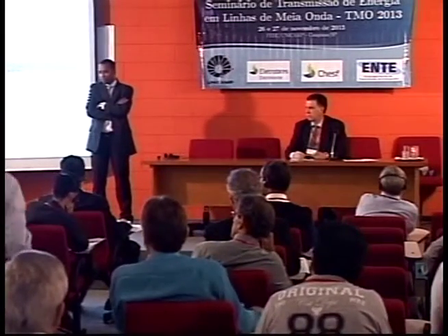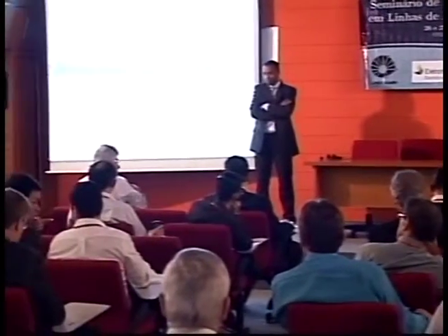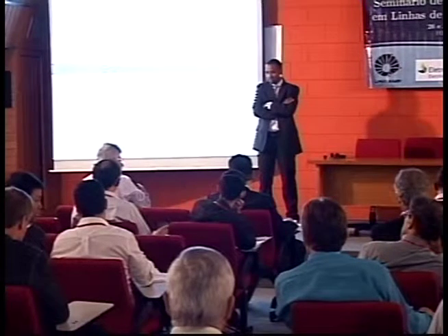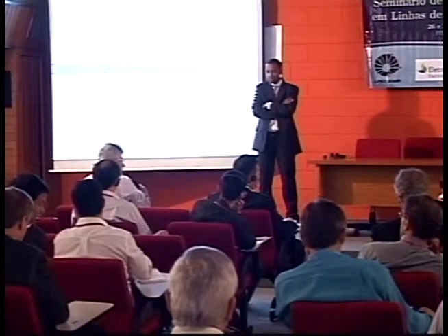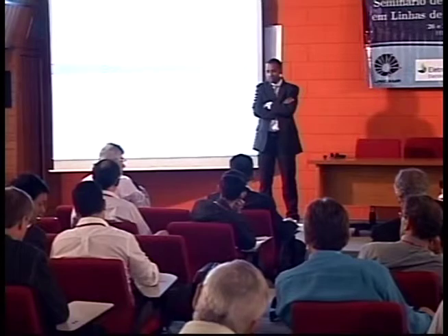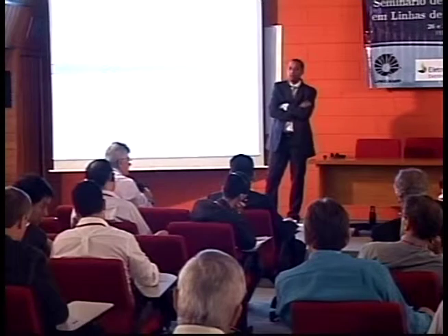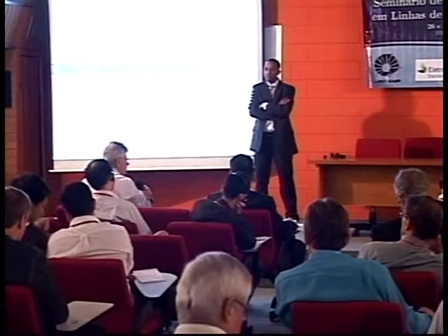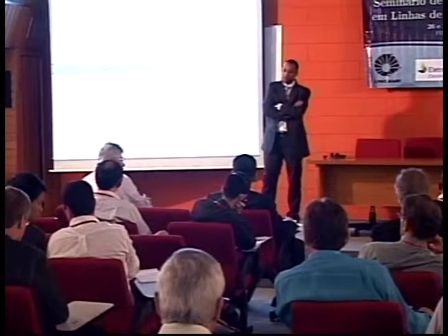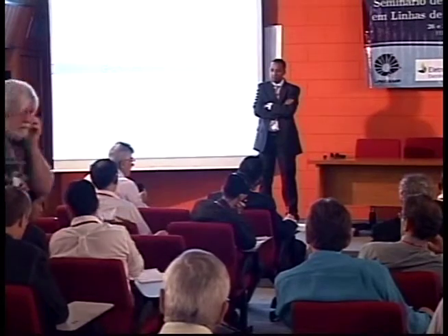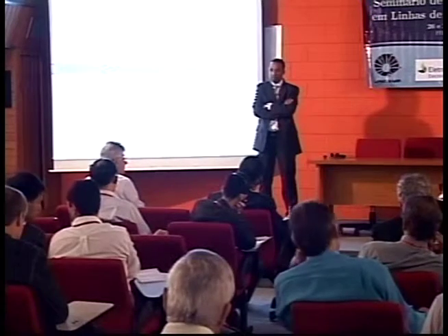This proposed test is a direct connection between generator, transformer, circuit breaker, and the other circuit breakers that are fixed in the substations that are closed, until reaching Bom Jesus da Lapa. This way, there is no need to model the substations because everything is in series, from the generator up until the terminal. So the modeling for this is not necessary. We don't need to model the bus bars in the substations since you're using the devices in series.